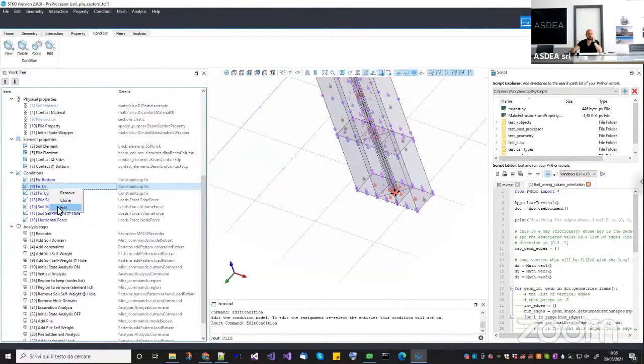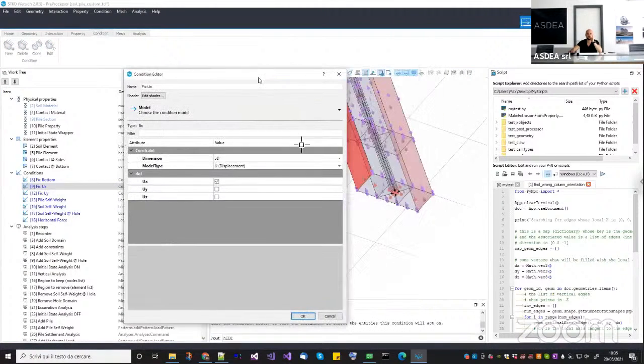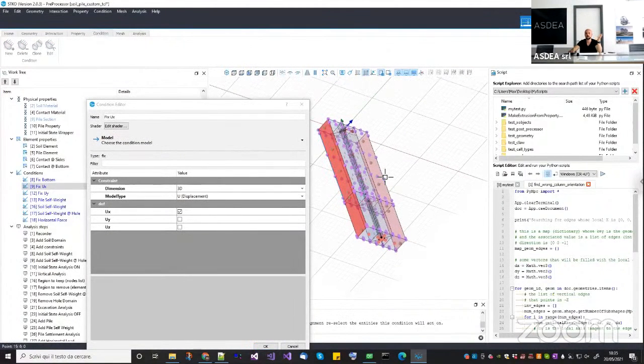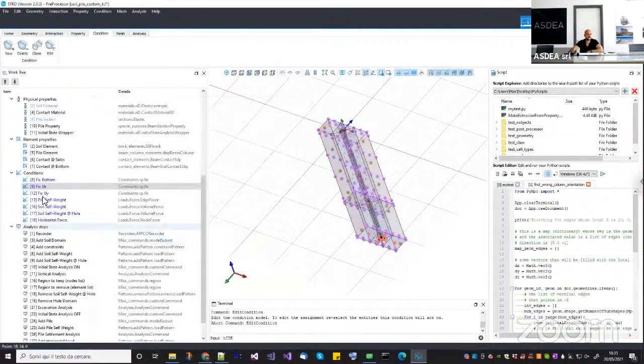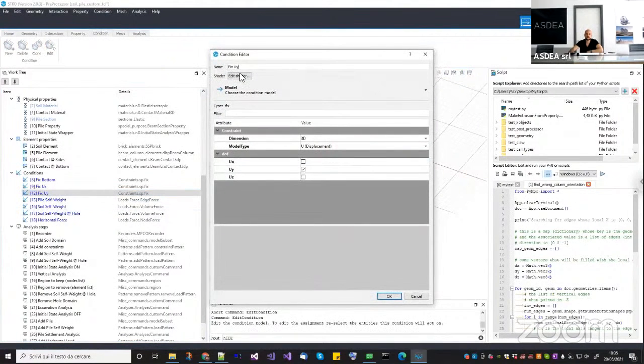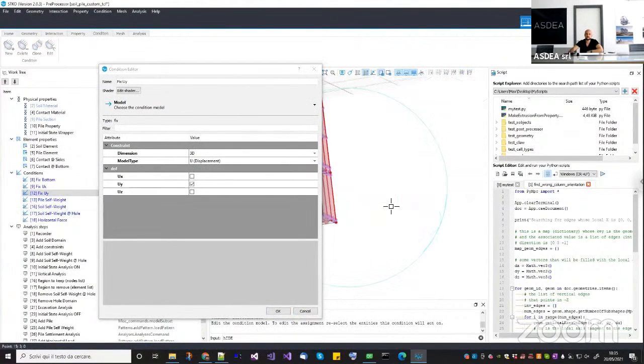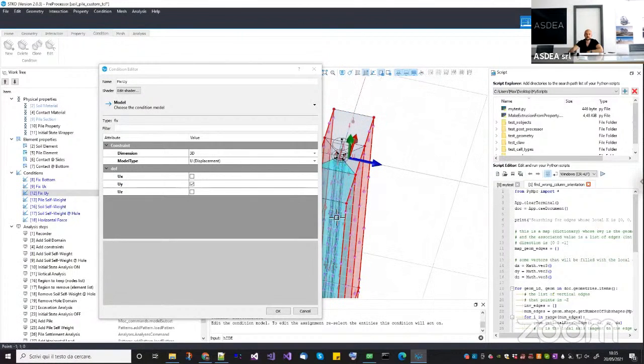The x displacement will be applied here, but you can use any other kind of boundary condition, okay? So this one was useful only to simulate a small piece of volume. So there is no x displacement in these two vertical sides, and there is no y displacement in the other two vertical sides, okay? So these two here, front face and back face.